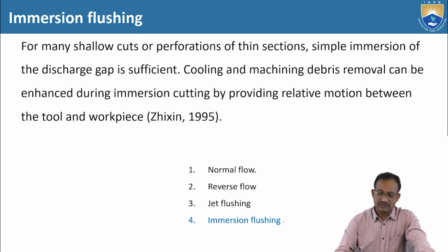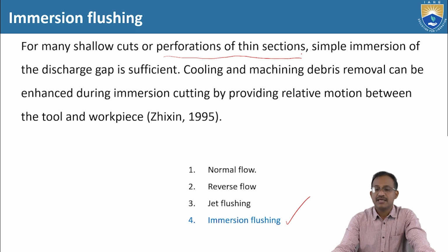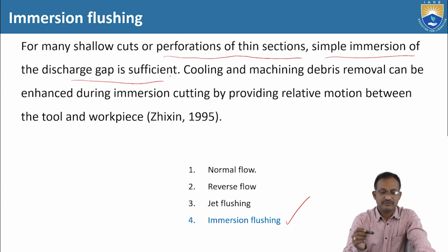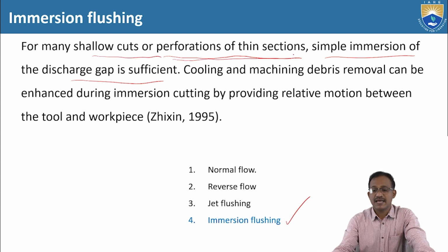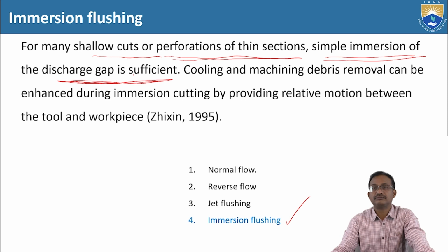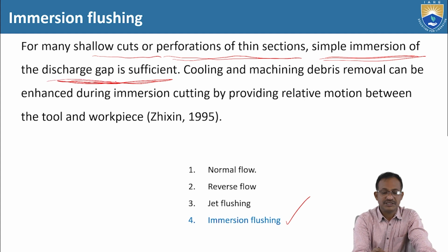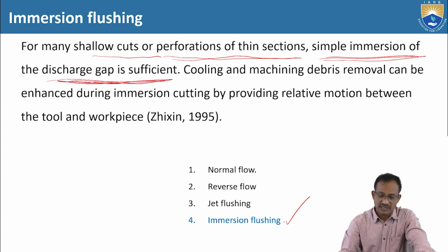Now let us discuss the fourth one, immersion flushing. For many shallow cuts or perforations of thin sections, simple immersion of the discharge gap is sufficient. Simple immersion of the discharge gap is sufficient, so that's why it is immersion flushing.